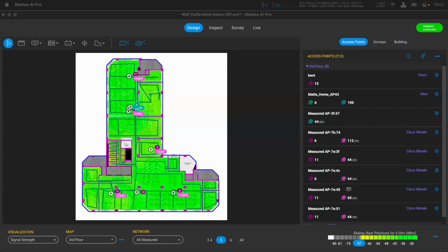Our amazing new wall calibration tool can save you so much time, and how it relates to the important part of step 1 in our 3 steps to great Wi-Fi every day. As part of step 1, a great design will require you going on site to get an understanding of the physical environment. There are a lot of factors for us to consider, from accurately validating the scale of your floor plans, looking at mounting locations for your beautiful access points, and of course understanding how the walls on site are going to affect the RF by form of attenuation.